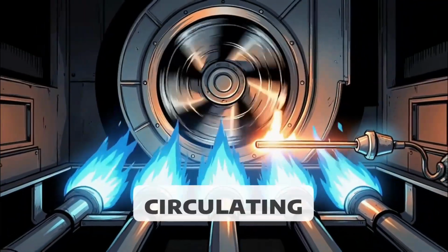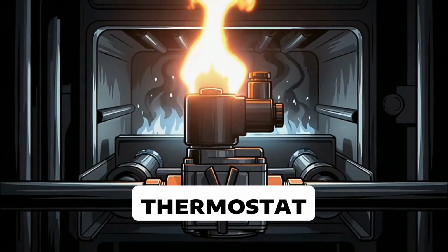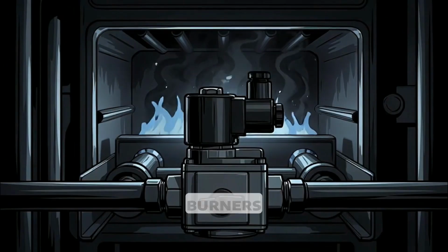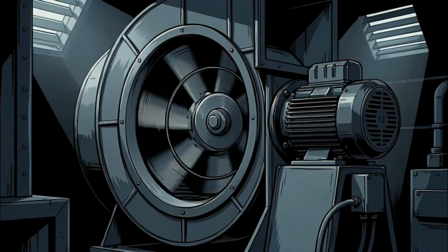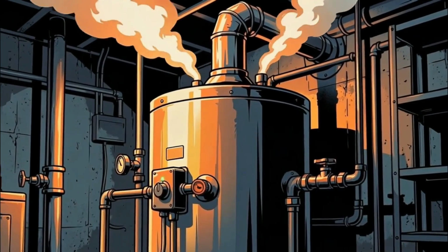Step 8. Circulating blower starts after a time delay. Step 9. Thermostat is satisfied. Step 10. Gas valve closes and burners shut off. Step 11. Blower continues for cool down, then stops. Memorize that order. What heats water, not air?